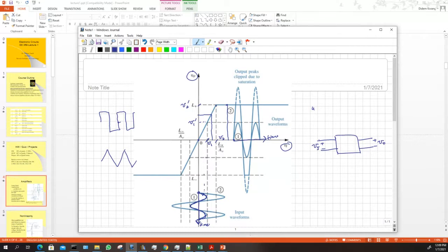If you map this using this point, I'm going to map it not over here, but over here, and I'm going to make it a time instance t later, right? You get this voltage at the output. If you give this voltage at the input, what do you get? You get this voltage at the output. So you can draw the output voltage when the input voltage looks like this. This is the input-output graph. You'll be drawing this for amplifiers, for instance op-amps and transistor amplifiers. It's just an easy way to see.